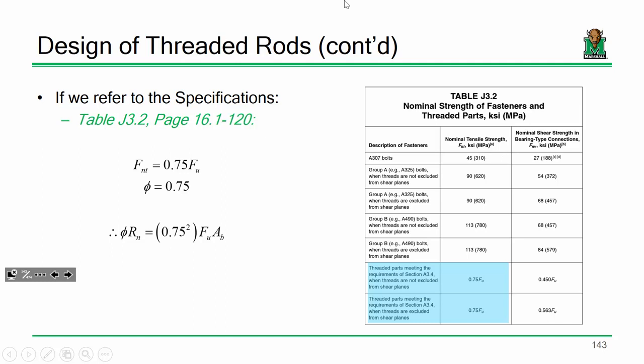But one thing you've got to be clear about is when you start going into the world of SI, a lot of things change. It's not a W12 by 35. It's like a W300 by 56 or so. I don't know. It's however many millimeters deep it is and how many kilograms per meter the section weighs. But you can do all this in SI. I don't. I just ignore it. But I guess the best answer is because you can. Is that good? Is that fine? Everybody else? So yeah, those numbers in parentheses are just the SI equivalent in megapascals. Okay. So far so good.